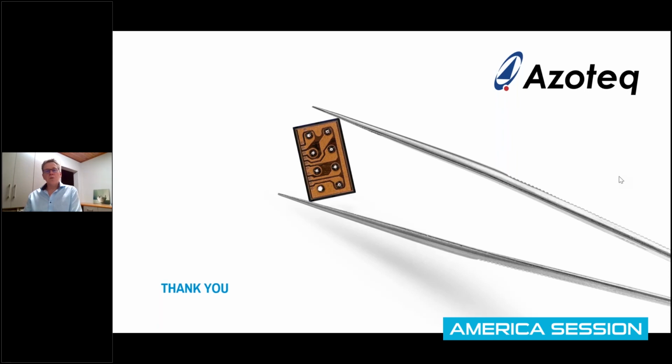If there is no moving part and the user literally has to cause a deflection in the top cover as he is sliding, then the precision will be significantly reduced and it becomes a function of the stiffness of the housing. But sure, we can still do the slider and it will still be applicable for something where you just want to use the sliding function, let's say to unlock the screen or something simple like that, where you don't need the high precision of the mechanical part moving.